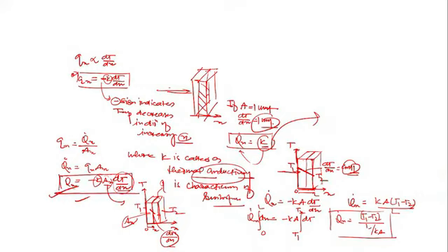And this equation of Fourier's law is valid for steady as well as unsteady state. This equation that you have written, it has no restrictions. Listen, this form of Fourier's law has no restriction. This form of equation of Fourier's law, q dot x equal to minus k A into dT upon dx, you can apply for either. There is no restriction. It's simply the general Fourier's law that can be used for steady state as well as unsteady state, even with generation or without generation. Even if k is going to vary with temperature or not, in all cases you can use this. Clear beta? This is the general equation of Fourier's law.